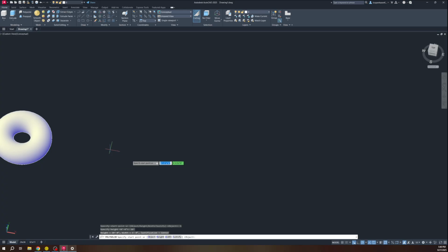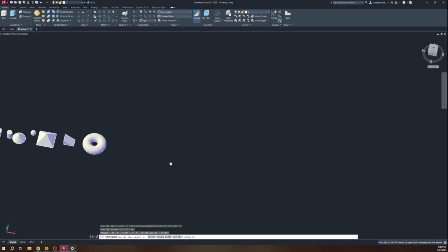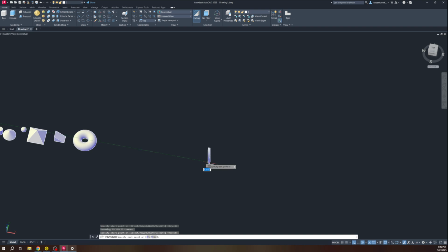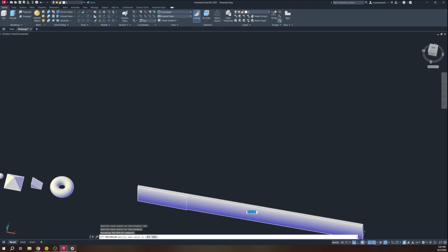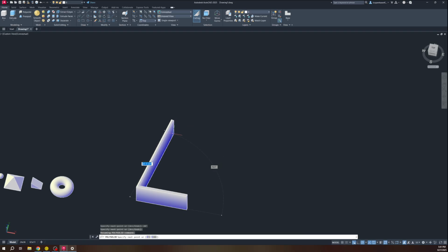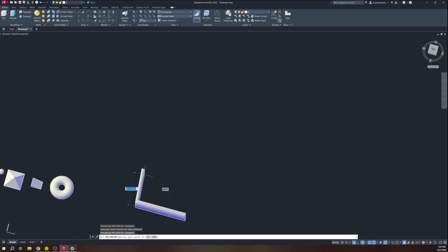Enter to accept that. And now when I click, I better scroll out, this is going to be giant. I have a wall that I can then just start to draw and specify. So maybe it's a 20-foot wall on that side. So it basically is like drawing with a polyline, except that the polyline has thickness and height, which is kind of awesome.